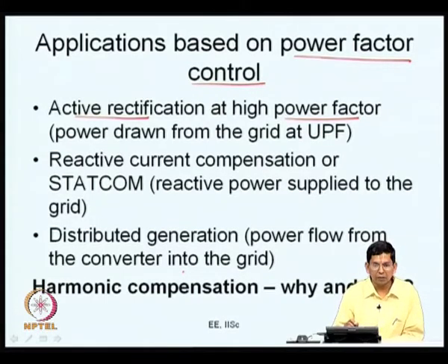Sometimes you pump reactive current, or reactive power, into the grid. You maintain the current to be leading the grid voltage by 90 degrees. So, this is what you do here.